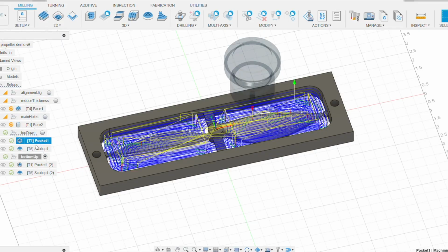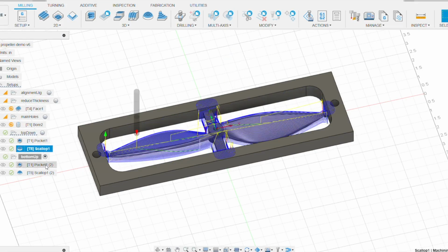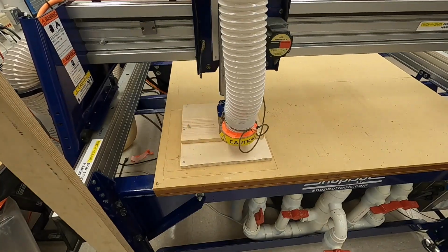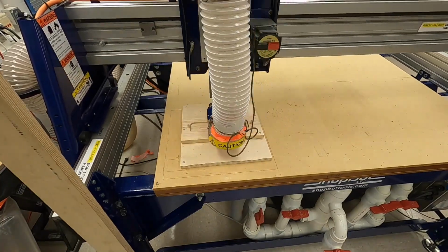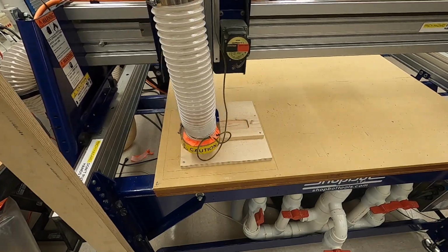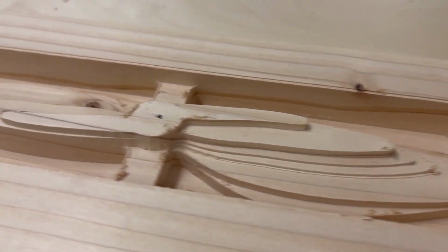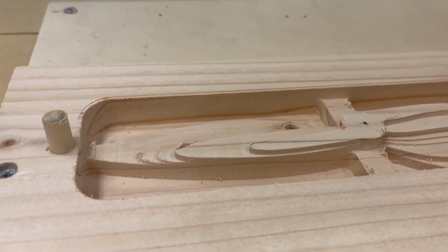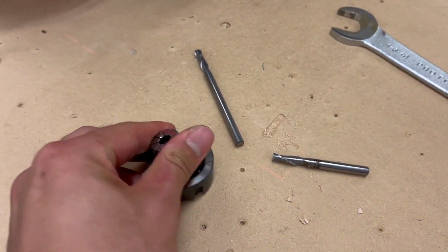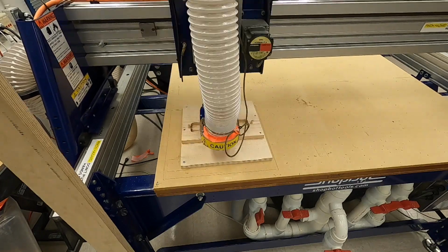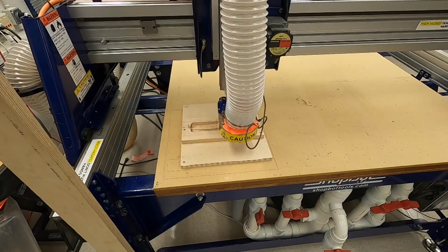Tandem then generates a roughing and finishing cut for each side of the main workpiece, 4 cuts in total. Once the roughing cut is done, the notebook prompts the fabricator to install a ball end mill as the current tool. They then flip the workpiece.